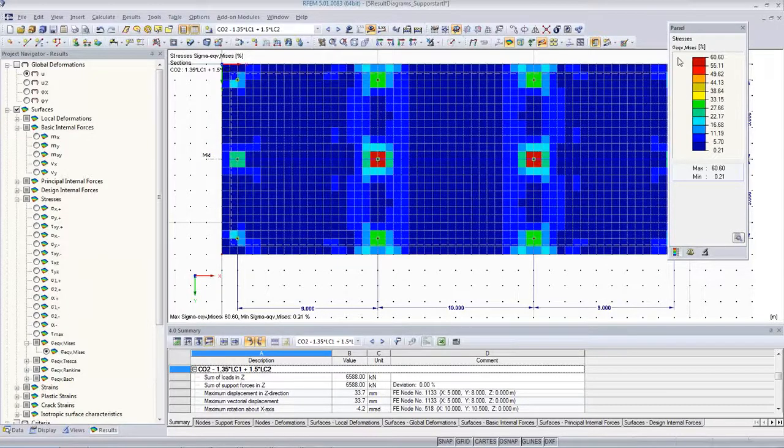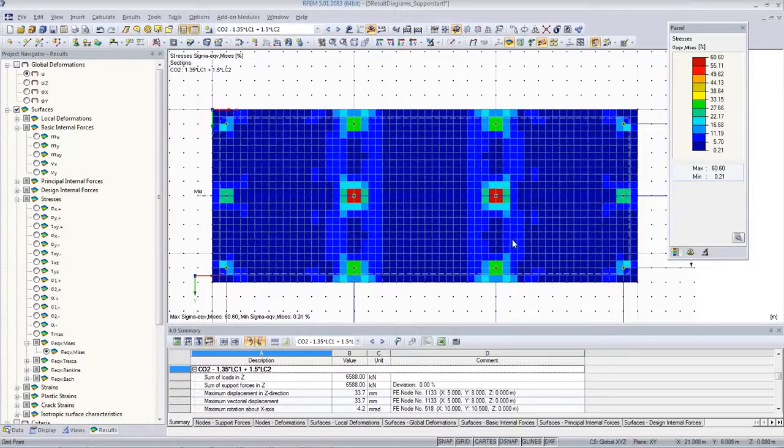So the stress gradient, where it is red, is 60%. So the increase from one element to the other one is 60%. So it's a location where there is a lot of increase in these values, where we have those peaks. And those are typically the problematic places. Here it's clear because it's a point supported slab, and where the point supports are located, you see the singularities. But in other structures, it's not so clear, but you can find it in this way.